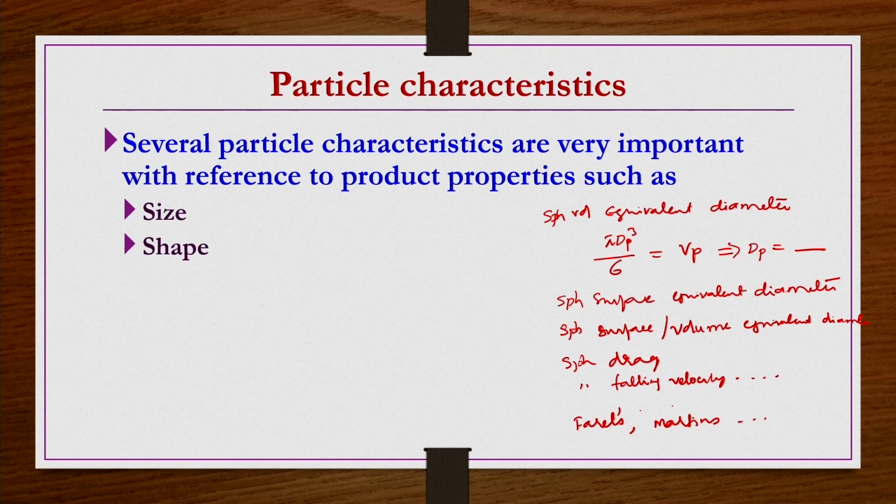These statistical measurements are in general obtained by microscopy, but that is not a practically applicable method in industrial applications, especially in process industries. Why? Because we have a relatively infinite number, that is, thousands of lakhs of particles in the mixture. So, you cannot take each and every particle and measure it under the microscope for analysis. That is the reason why, though it is a reliable method, it is not going to be helpful.